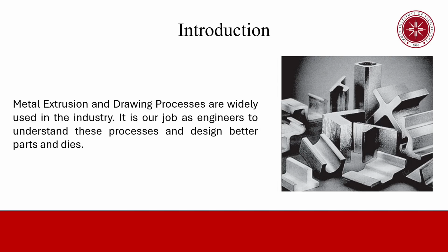As we have seen, the way metal flows during the process has a massive influence on the final quality and properties of the product. When the flow is disrupted, or when process variables such as temperature, speed and friction are mismanaged, we encounter significant defects. Today, I will detail the three primary categories of extrusion defects: surface cracking, pipe, otherwise known as fishtail, and internal cracking, often called chevron cracking.